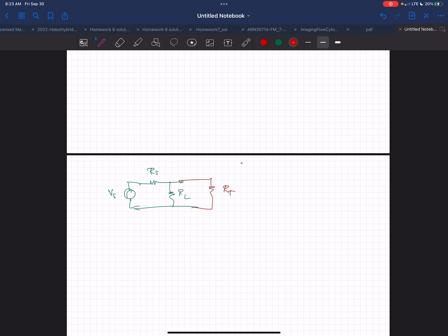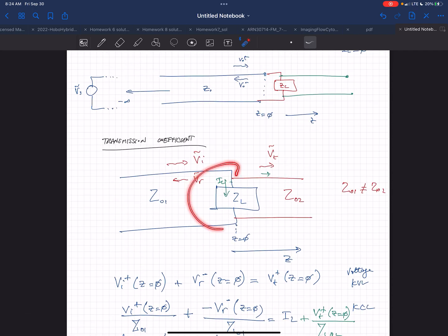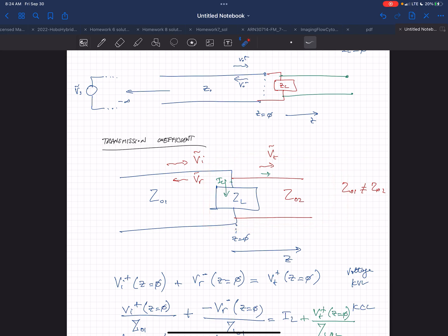That's going to affect the voltage here. It's going to affect the impedance looking into this point, whether this one's here or not. This is a lumped version of what we're doing here. Initially we just had this as the load. When we put the second transmission line here, it's going to be in parallel with this. So you have to include that in your thinking about what gets reflected back. Everybody good with that?